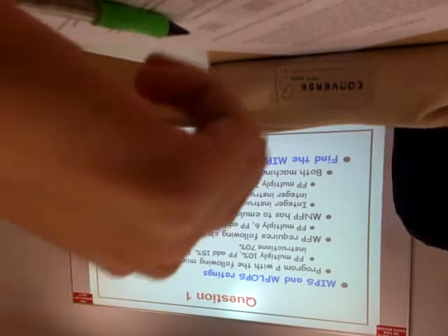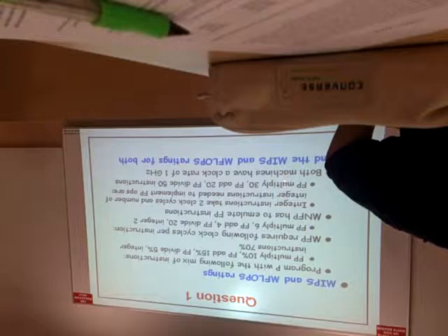The other machine, NFP, has no floating point unit. So for this machine, we have to emulate the floating point instructions using integer instructions. The integer instructions take 2 clock cycles, and we need 30 integer instructions for floating point multiply, 20 for floating point add, and 50 for floating point divide.